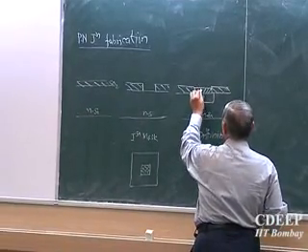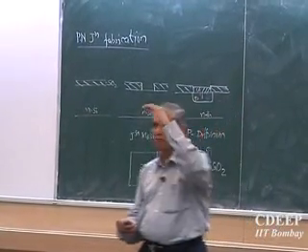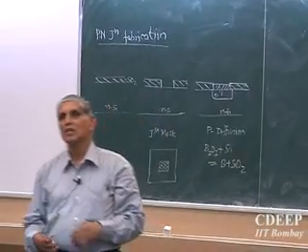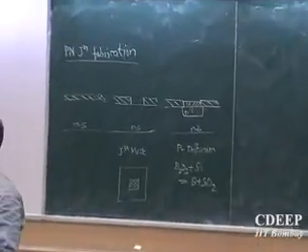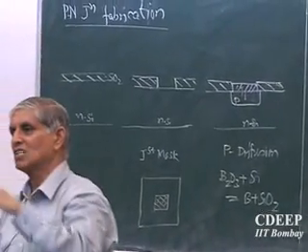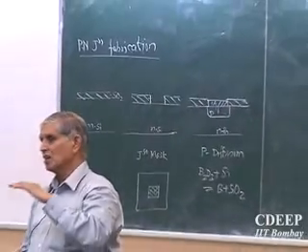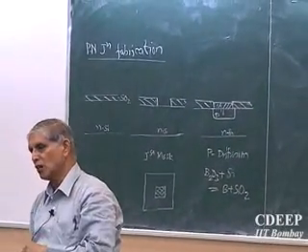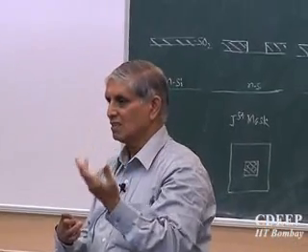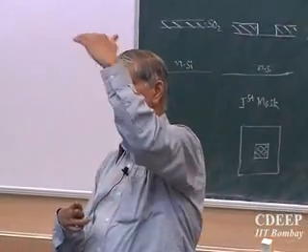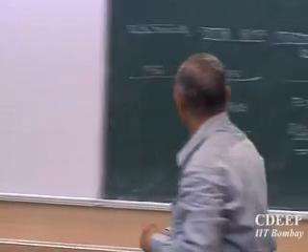Start going this side and SiO2 will keep forming upwards. The advantage of this SiO2 is that boron now cannot leave on the upper side because SiO2 will block it. This is a natural thing that happens, so great for us. In the process, the boron starts diffusing down, and the oxide stops it going out. Otherwise by diffusion it can go either side. Is that clear? Diffusion is a random process, but the upper one will now stop.